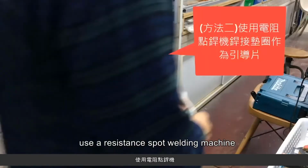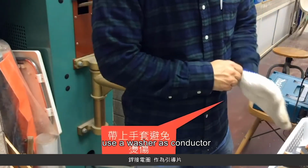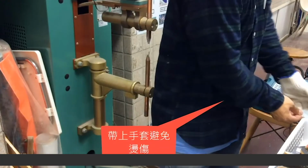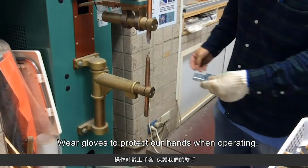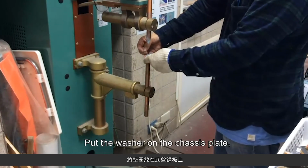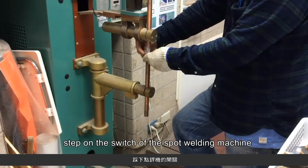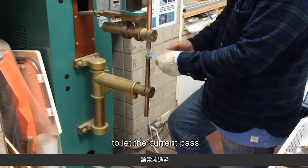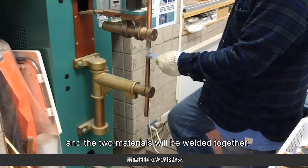Method 2. Use a resistance spot welding machine and use a washer as conductor. Wear gloves to protect our hands when operating. Put the washer on the chassis plate. Step on the switch of the spot welding machine to let the current pass, and the two materials will be welded together.